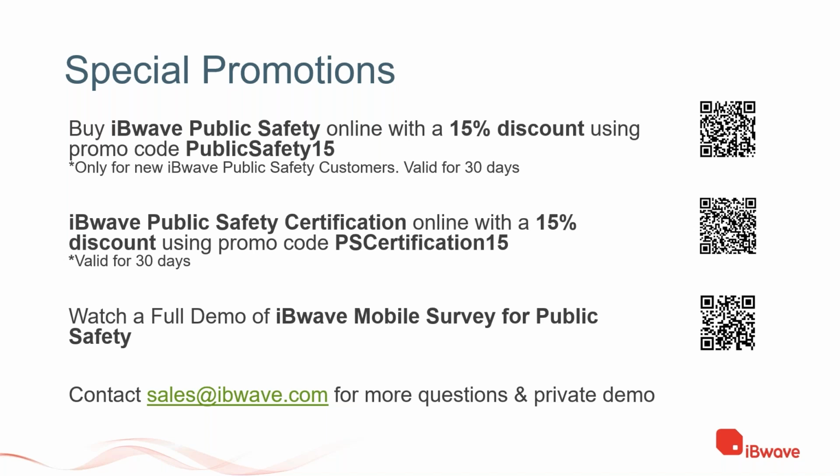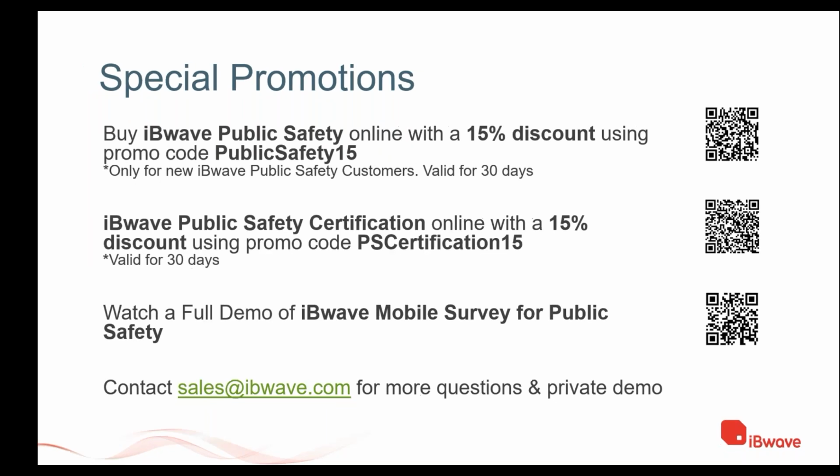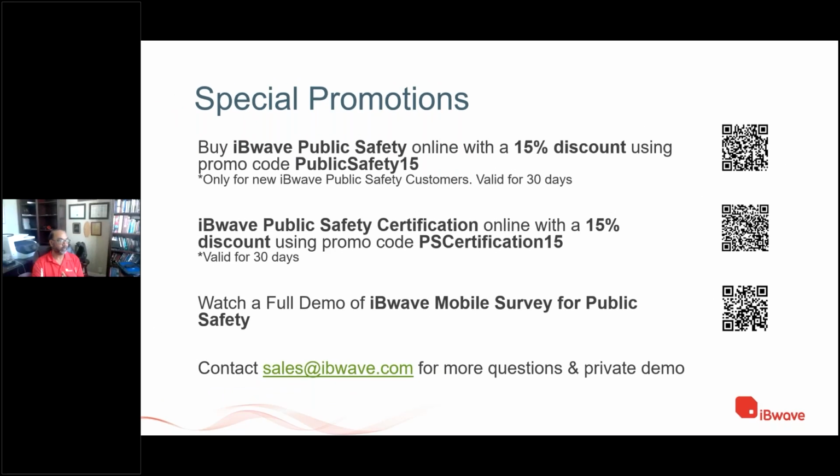Traditionally, a lot of design engineers, including me, didn't know where the head end would go, so I put the head end somewhere, and then I put my antenna somewhere, and I connect the cable. So when I don't know the starting point and end point, IBwave automatically creates VIA for you. But if it's the same building, IBwave creates risers for you. That's the reason it's very, very important.